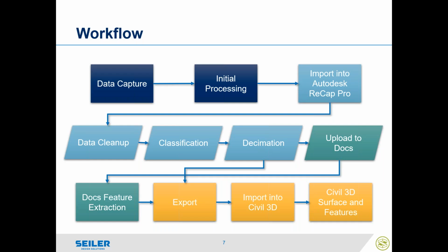Autodesk removed the ability to directly import LAS files into Civil 3D back in about 2018. Even then, it was kind of like you could get a DEM. Everything was converted to a digital elevation model and extracted from there. Now with ReCap, we can bring that point cloud directly into Civil 3D if we want to, and use that as a background reference, or use things like Autodesk InfraWorks or Revit to model buildings off of. But we have to touch upon ReCap Pro.